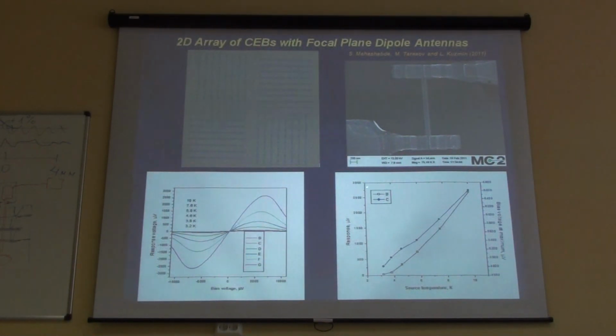So the signal is at the level of 3 microvolts. It's quite good for our measurements. And we created 8 by 8 in each segment, that means 128 bolometers in total. And we can see a very reliable realization. You see a very good structure of these bolometers, very clean, no problems.